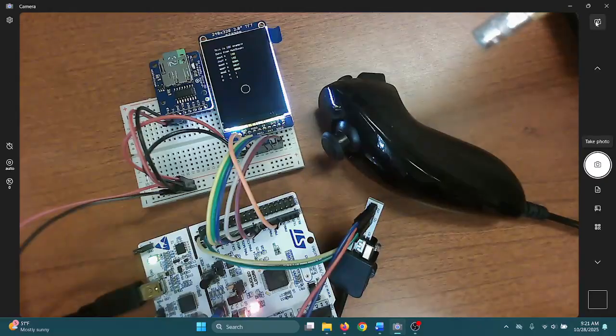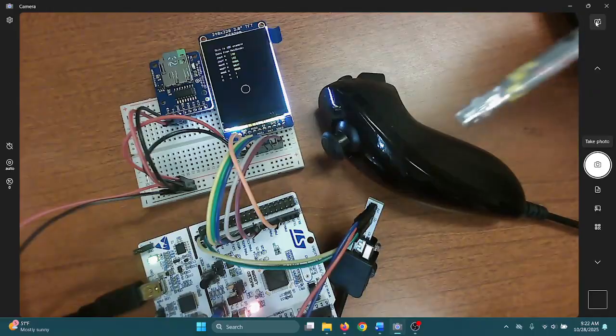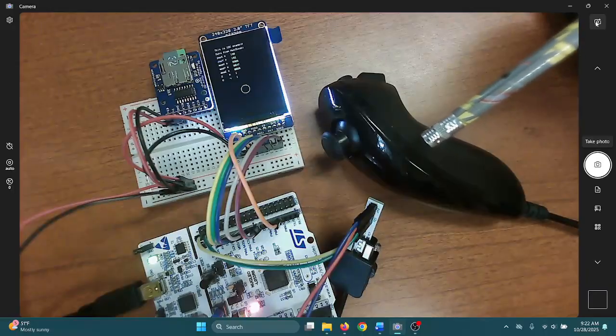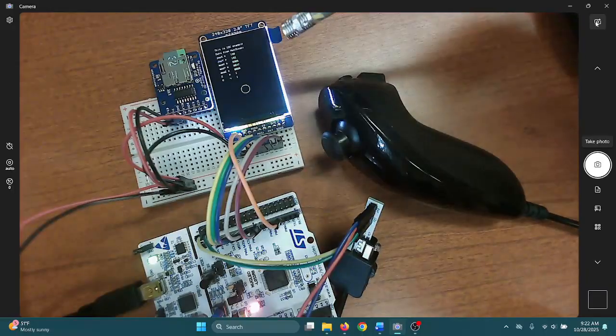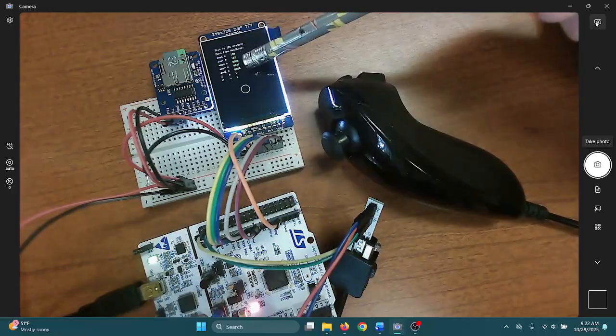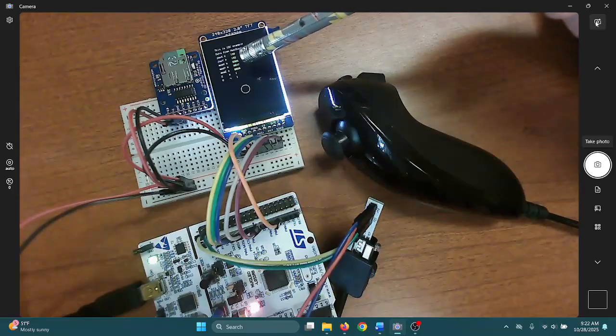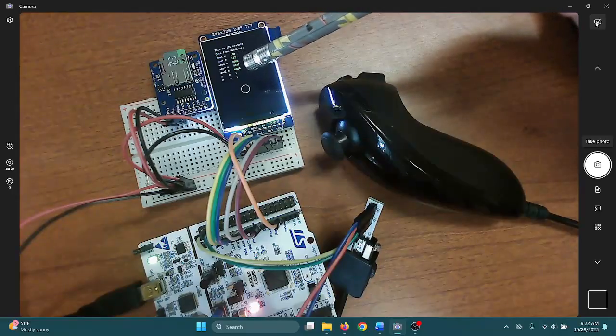whatever have you. And in this case, this is an example in a lab in one of my courses in which I'm reading and polling repeatedly the Nunchuck. I'm reading the data and displaying it right here on a tiny LCD display, where I display the joystick X, joystick Y, as well as the accelerometer data X, Y, Z, and the status of the two buttons Z and C.